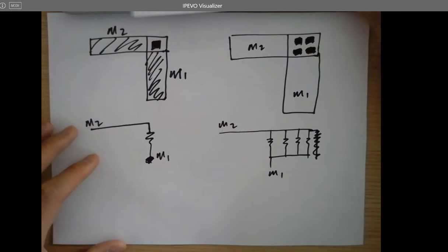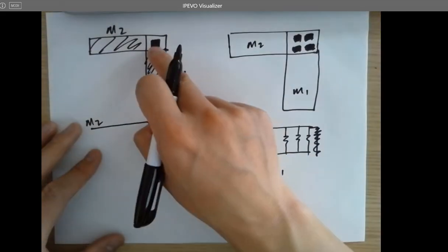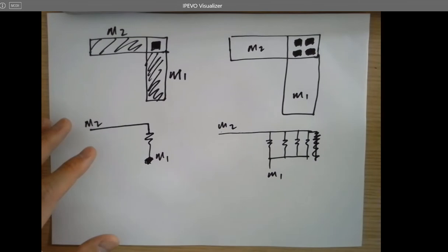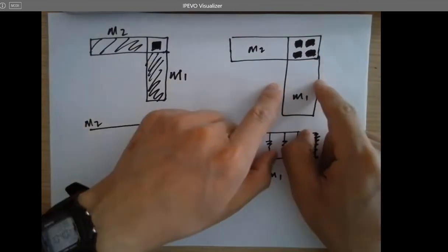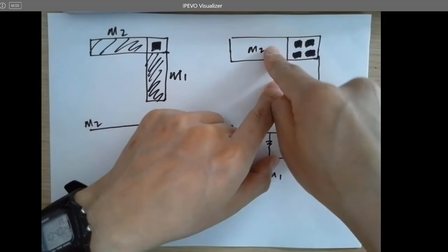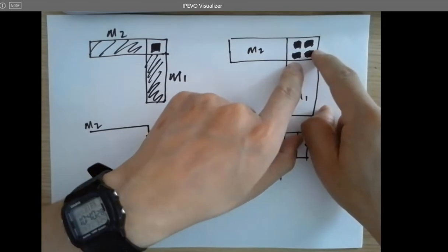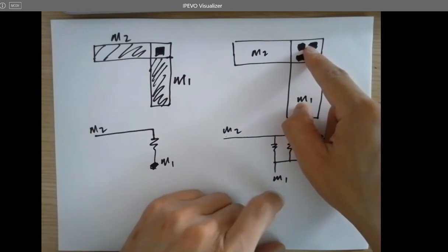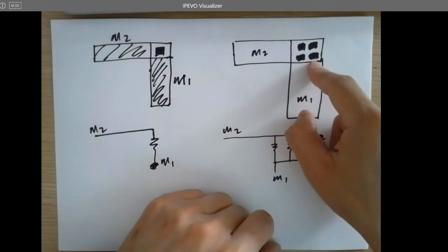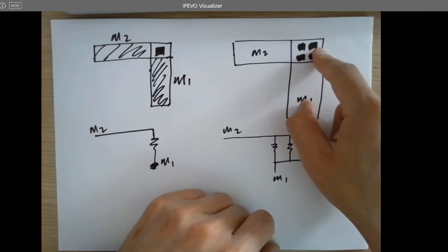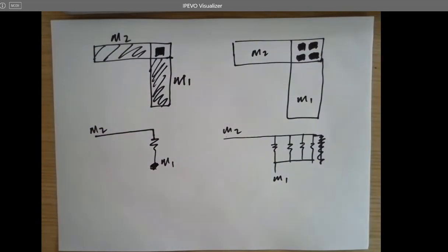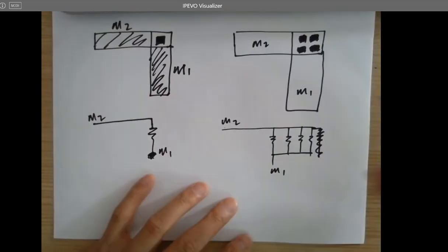What's the benefit of using 4 vias instead of 1 via? Because whenever you change the size of the metal and you want to make the connection from metal 1 to metal 2, Electric VLSI can directly generate a via array for you. So you are not actually doing this by yourself. It automatically generates all the vias for you. Have you ever seen this? You probably just never thought about why it's doing this for you. So there are several benefits of doing this, right?